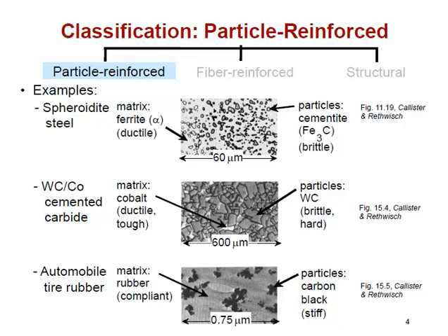Generally, particulate reinforced composites on this scale would be spontaneously formed through thermomechanical treatment of usually a metal alloy or a ceramic. You can add very fine powders to polymers, provided that you have matching surface energies, so you can add ceramic powders to a low viscosity polymer matrix and also achieve the same type of strengthening there.